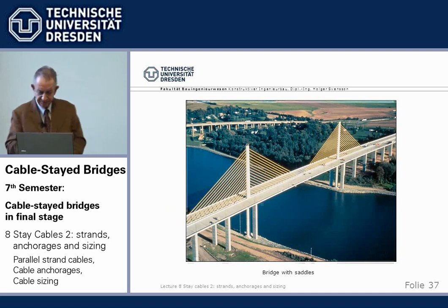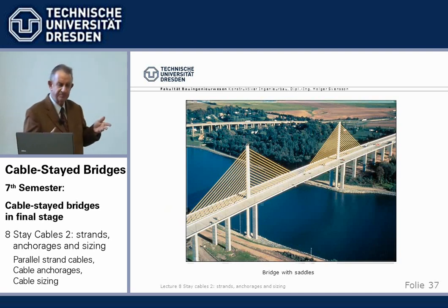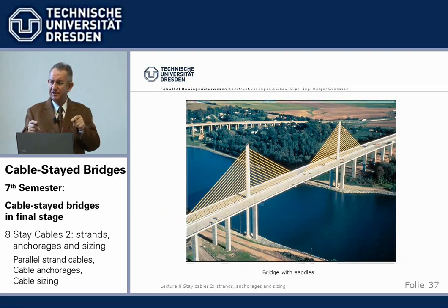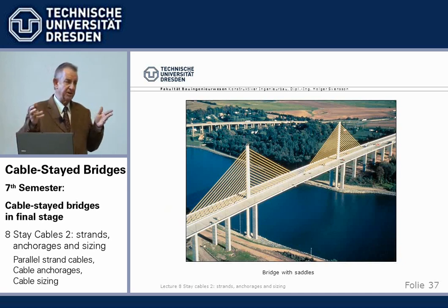I start with the more unusual, and that is that we anchor the stay cables at the tower not separately, as we normally do, but we have them continuous, running through from the beam through the tower again to the beam. An advantage can be that you save the 2 cable anchorages at the top by going through continuously. It's always cost which is behind these crazy ideas.